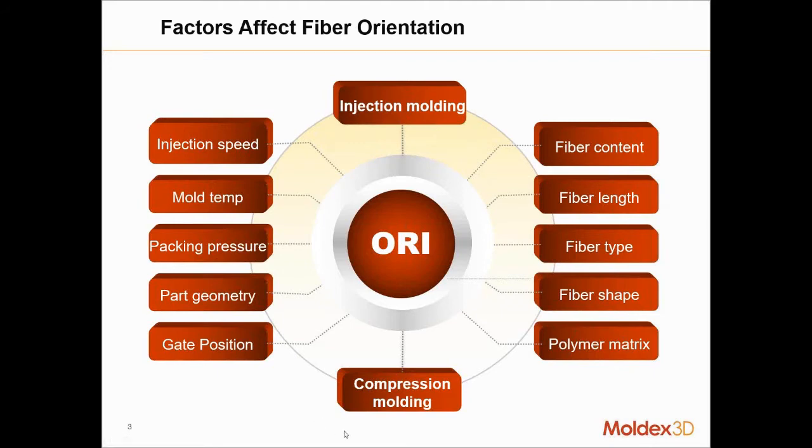But to control fiber orientation the best, compression molding is definitely the hallmark way to do that. So we get a charge that has some sort of preset fiber orientation, and then that charge is simply pressed into the shape that we want it to be. And that fiber orientation is much more easily controlled. So these two are definitely the leading processes that will allow us to take a look at or to control reasonably how the fibers are oriented in the part and study how the part strength is going to be impacted as well as the part weight.